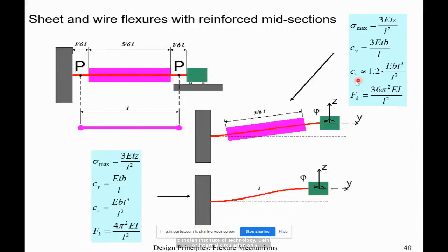And if it's 1/3, then we will get a square of it, right? So that's why we are getting 9 times more load bearing capacity, because it's related to L, right? And it's in the denominator. So if the length is decreased, the load bearing capacity will increase a square times, ideally, right? So we are gaining here a lot just by reinforcing them, and that's why many times we go for reinforcement.